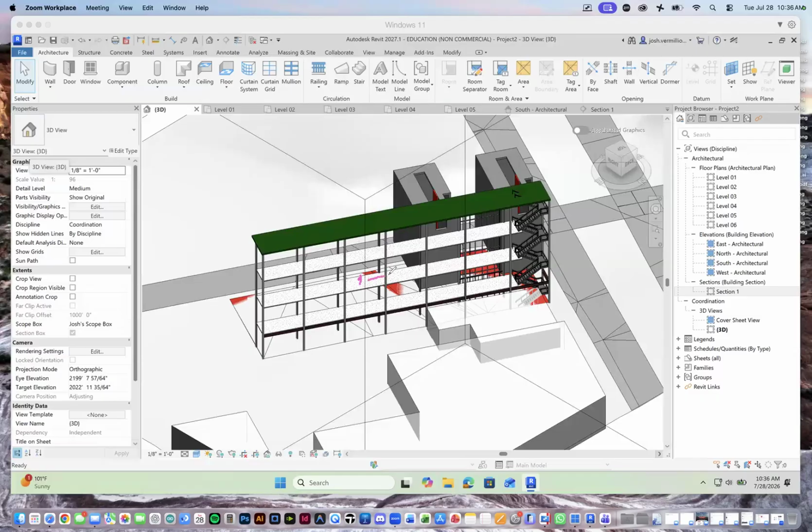Anyway, essentially that's what we think about when we're talking about life safety. If I'm a person here, do I have two safe ways to get out? In case one of them is blocked, the second is an alternate way. So when we have a wing like this, that's what I keep talking about, how we think about the logic of circulation. It's not just getting you from point A to point B, it's also a degree of life safety involved when there's an emergency. We need to make sure that we have fire-rated ways to get people out within an hour or two and safely away from the building. And so we'd probably want to put another stair over here, a stair tower in this direction.